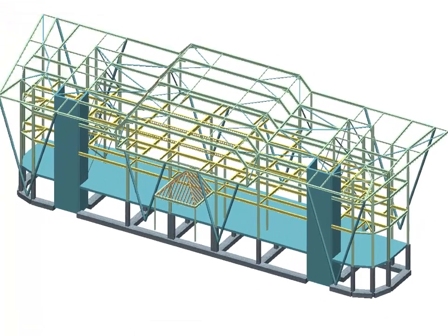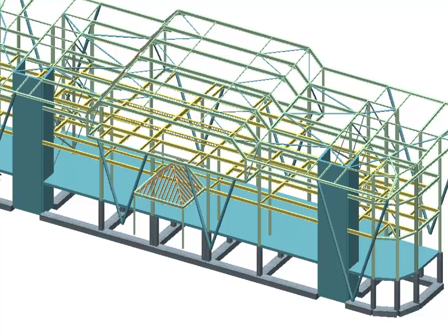So what I've got is a first floor that's a finite element transfer slab, because if you look carefully you will see that this column is not coincident with this concrete column below. So the superstructure is offset from the substructure. So we're using this FE slab as our transfer slab. We also have concrete ground beams,